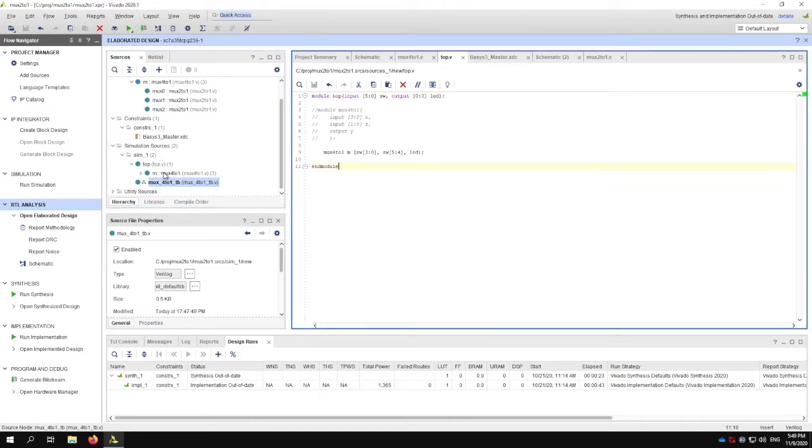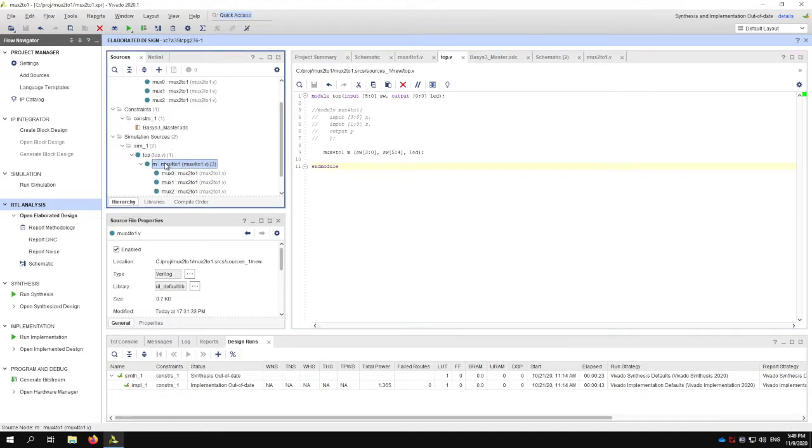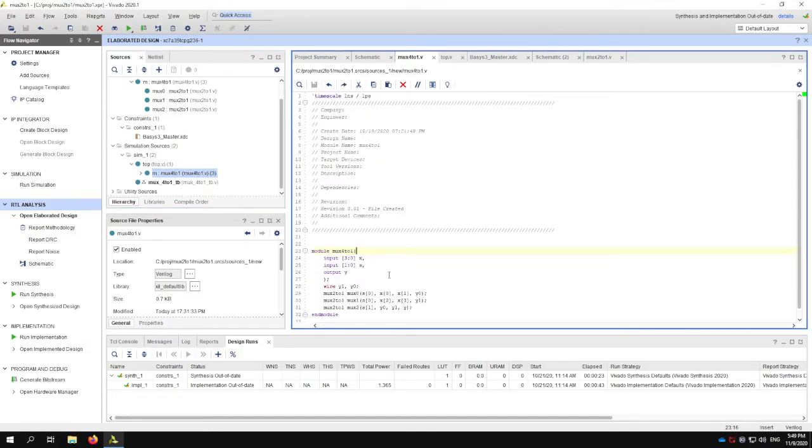The first thing I'm going to draw your attention to, actually, in my MUX 4:1 is this timescale directive. That backtick over here indicates a timescale directive. We've never really talked about this before, so I'm going to explain what it means. The first parameter, 1 nanosecond, is the time step for simulation. And the second parameter specifies how fine-grained my simulation is.